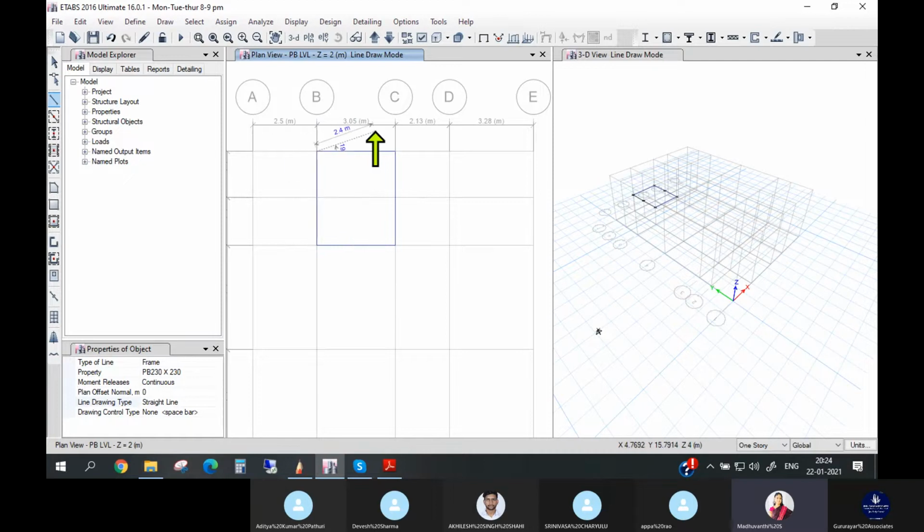Okay, so if you want to now temporarily disconnect this draw option, so you have to right click this. So after drawing this, you want to disconnect this draw cursor, and you want to draw the beam somewhere. So in that case you have to right click it. So I am right clicking it, so it will go, right? So I have drawn this portion.